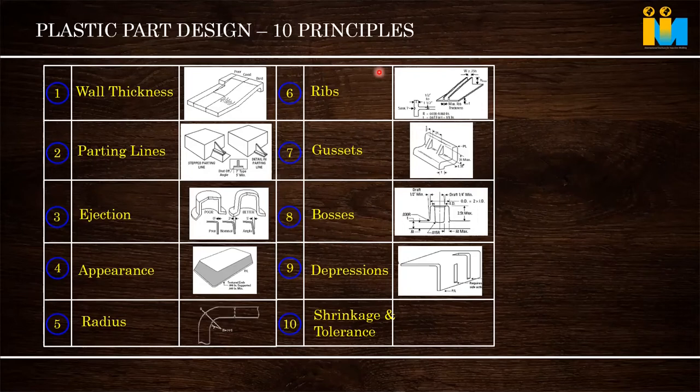But in some cases, you have to go higher because higher pressure is getting built up. It is a pressure chamber. You have to go for 10 mm. Then based on that, you have to give cooling. Sometimes you have to go for conformal cooling. Sometimes you have to put it in the water, take it out and anneal it again to remove the stress. All these things have to be done. 2 mm, 2.5, 3 mm are a good amount of wall thickness.